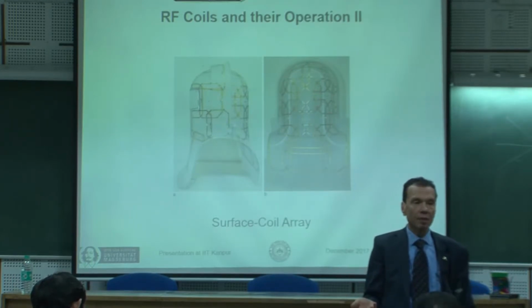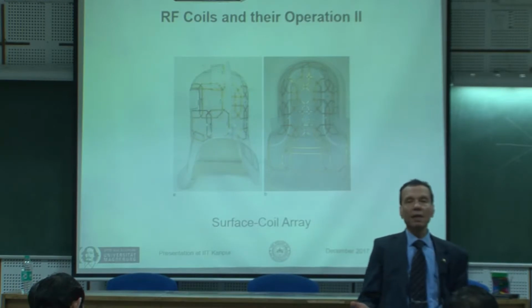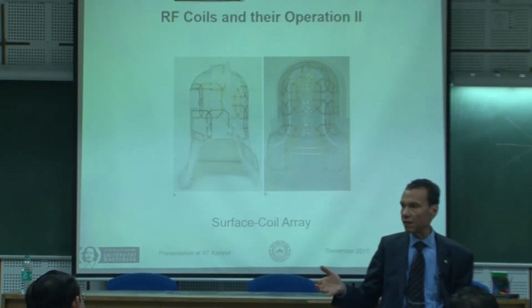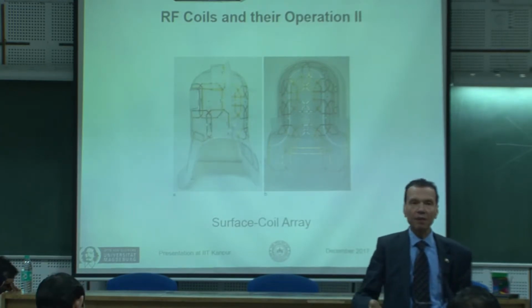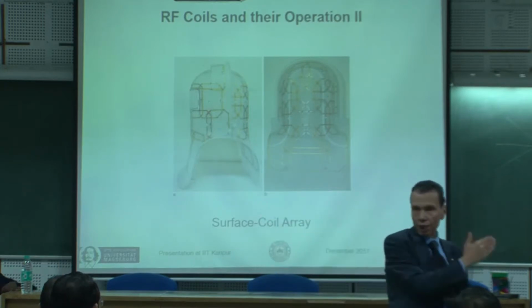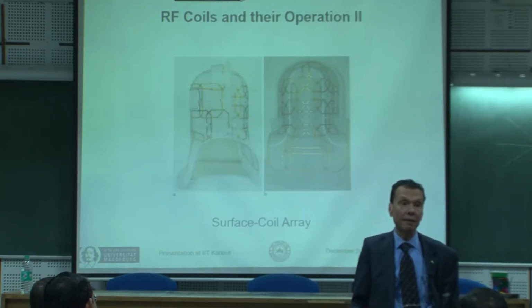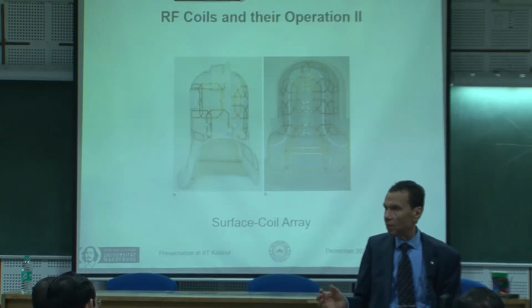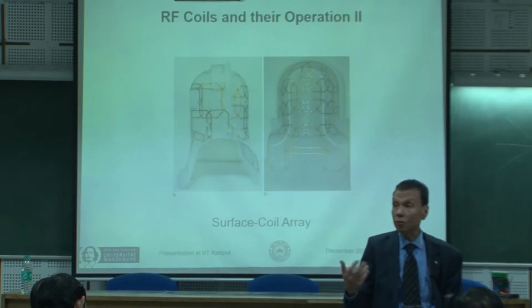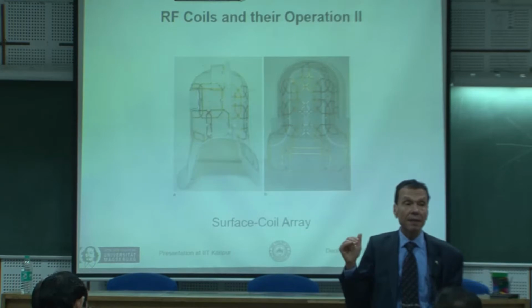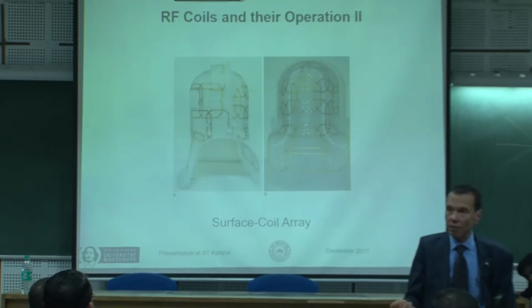Which signal to noise ratio should you use? It's exactly a communication problem. For those of you who are acquainted with communication, the very first system after the receiving mechanism, after the antenna, should be an amplifier, a low noise amplifier, because this dictates the signal to noise ratio for the entire chain afterwards. So in the receiving chain, we have, or should have, a very, very good LNA. Narrowband, of course, because we would like to minimize noise, and with very high amplification in order to see the signal level of minus 110 to minus 120 dBm. So signal to noise ratio is an issue.